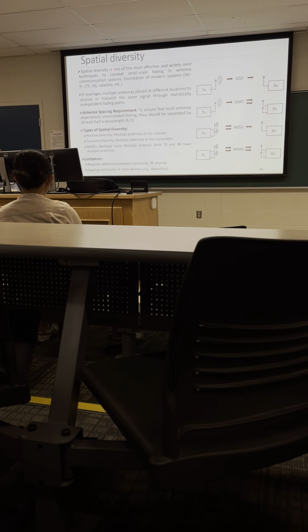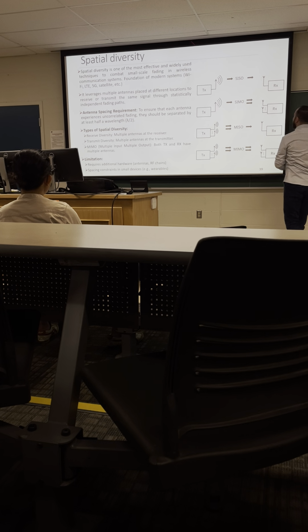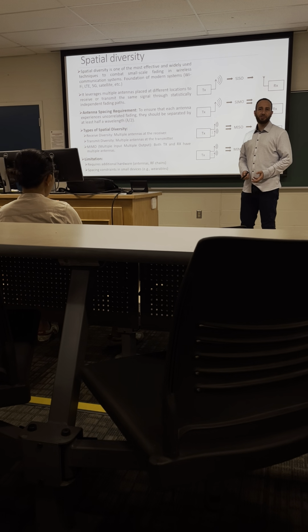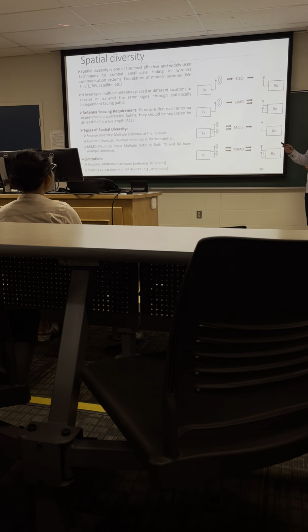The limitation of using spatial or space diversity is that it requires additional hardware. As you can see here, instead of having one RF chain, this chain from the transmitter to the receiver, called the radio frequency chain, we need more. This chain in practice is very costly.